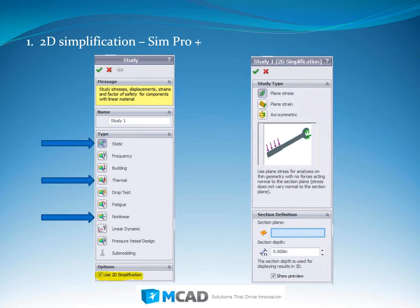And the way it works, when you select that option, you'll get a second window that allows you to finalize the setup, because we can pick between 3 types. We can have plane stress, as shown here, and this little simple representation of a wrench, and then a plane strain formulation of the problem, which would be something like a long member, like a dam, where you're taking a cross section through the dam.